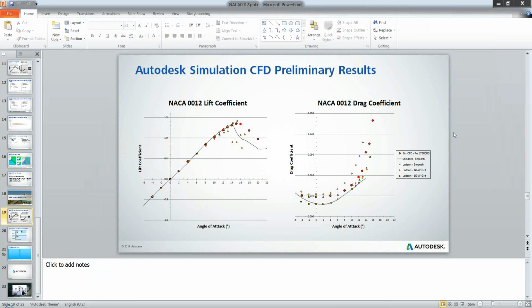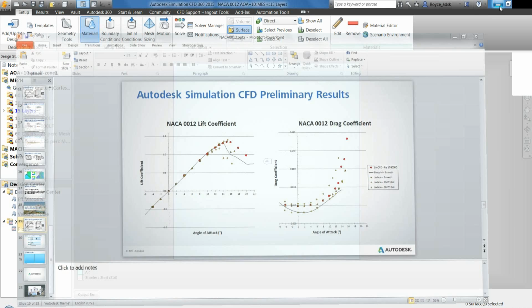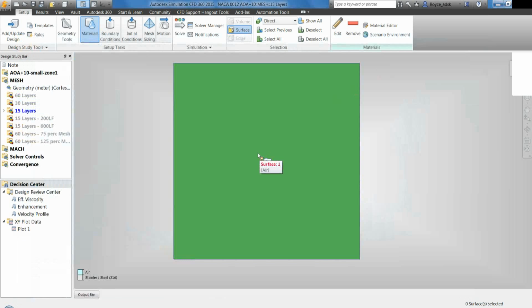I thought I made a note in there. Either way, it went from about 2,000 iterations for default to 5 for the ADV1, or the extra order of magnitude, or sorry, 5 for the tight, and then 1 order of magnitude went to 6 or 7, and then 2 went to 8 or 9,000, and then when you went to 3 orders of magnitude, it actually went beyond 10,000 iterations. I had to continue the run once it actually hit that. So that's why I say 1 to 2 orders of magnitude should be more than enough.